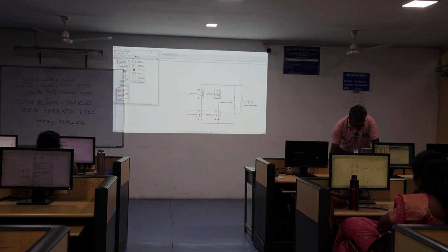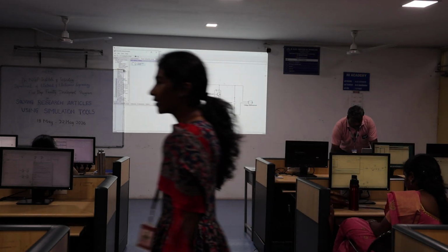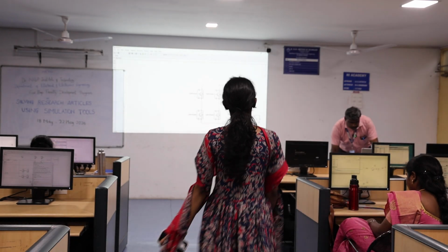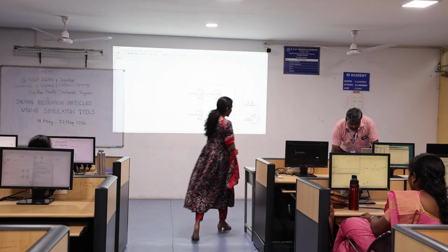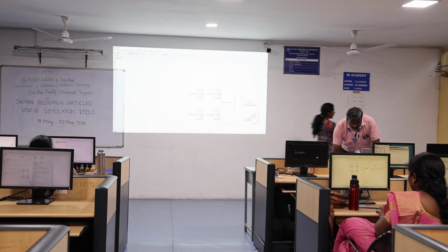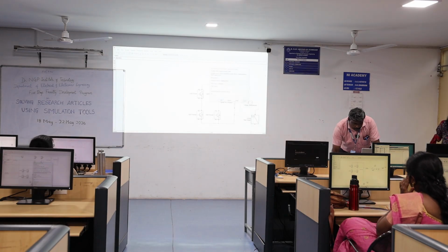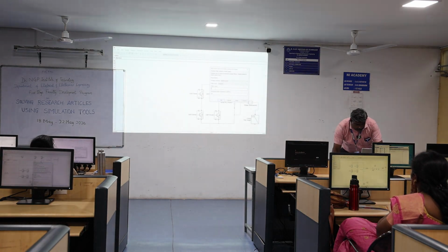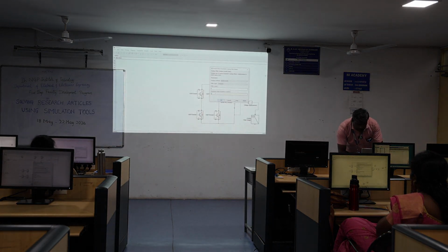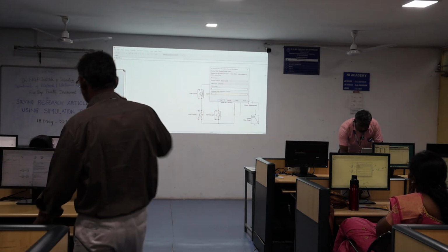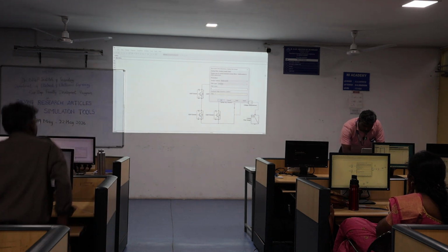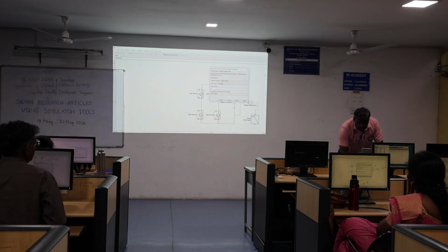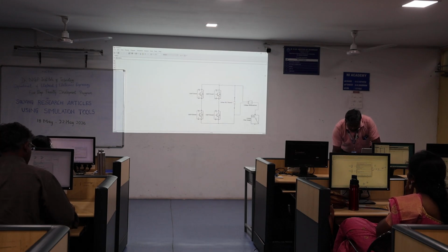Next go to the analog filter design. Let us take the frequency 5 kHz and convert it to radians. Let us take a low pass filter, 4th order system. Then 2 times pi times 5 kilohertz. Convert it to radian per second. Just enter it in radian per second. You have to put pi, okay?